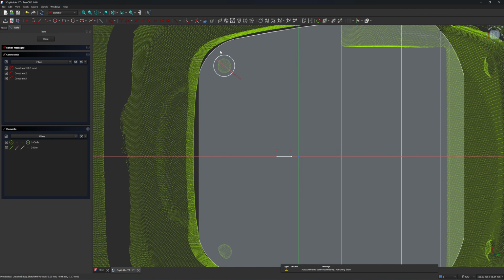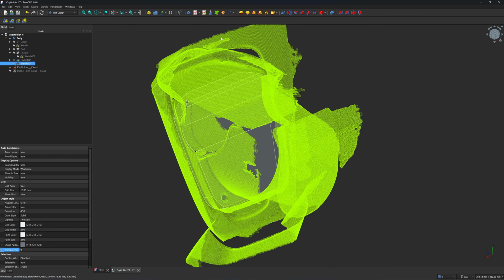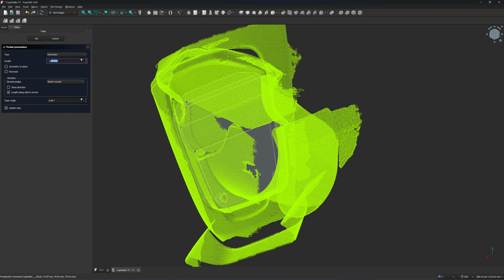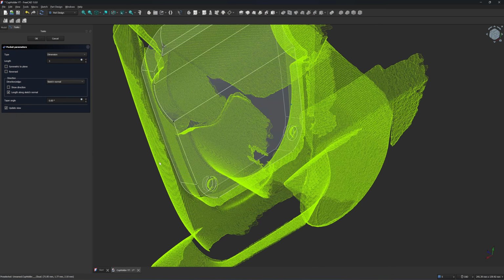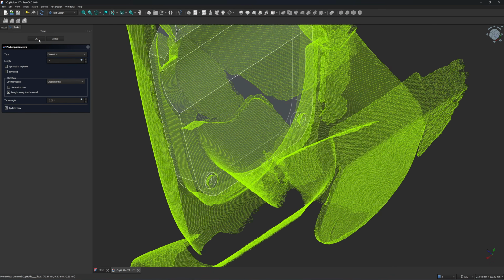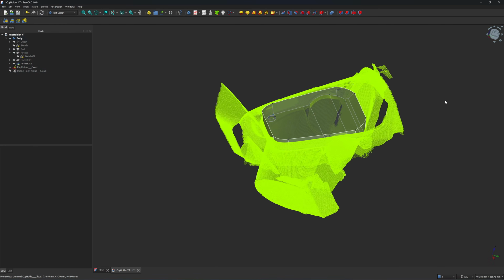I draw a mirror line. And then I'm going to mirror it to the other side. It doesn't match perfectly, doesn't matter. It should fit. And I'm going to delete the mirror axis. Close pocket. Cut it for 3 millimeter. Okay, 3 millimeter cut. Click OK. Okay, now it's done for the base.